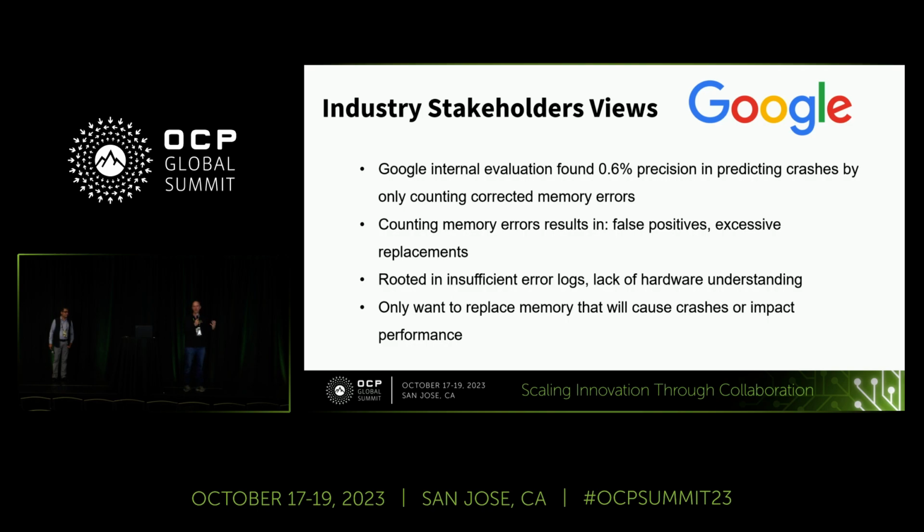the deal is that if you count errors, the error detection in the system is entirely dependent on whatever your software was accessing. So if you access a stuck cell in memory, you can drive any memory counter to any value you want. And sometimes software does that. So counting corrected errors weighs a single stuck cell in the DRAM, which, by the way, the error correction codes in the CPU will correct indefinitely, like for years, forever. It weighs that the same as a rank is failing and I'm getting a boatload of corrected errors and I'm about to crash. So you have a wildly different scope of damage and you have a variable that doesn't allow you to distinguish between the two of them.